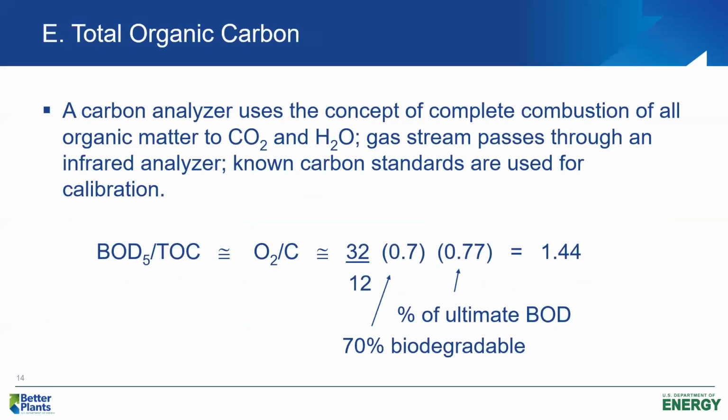Total organic carbon is a third way that we can measure organic matter in wastewater. One thing you want to remember here is BOD and COD measure organic content in terms of oxygen equivalents. When we measure TOC, total organic carbon, now we're measuring organic matter in terms of carbon, okay? So we have to be careful about how we relate BOD and TOC, because BOD is measured in terms of oxygen, TOC is measured in terms of carbon.